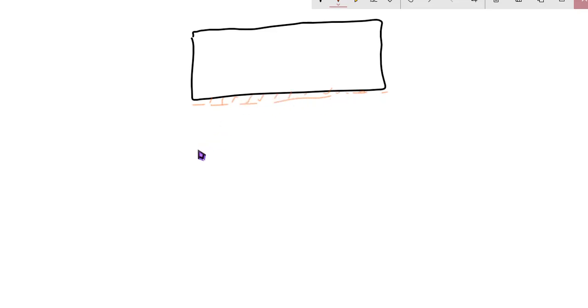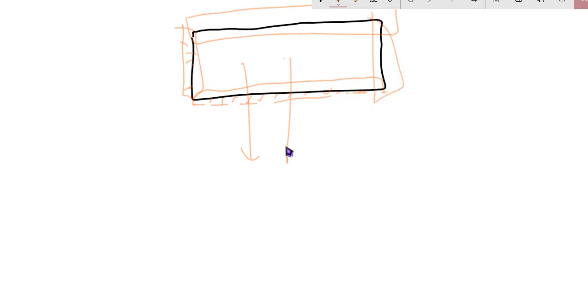So which means if the slab is bending, a portion which is attached to the beam will stay right in its place. As I'm drawing a one-way slab, in this case the bending will be something like this. As the corners are restrained, the corners won't bend. The bending will always happen inside. If I take a cross section of it, the bending will be something like this, as here is a beam, and here we got a beam. So this portion won't be bending.